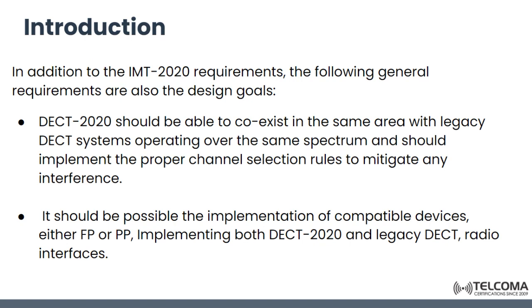With the help of DECT 2020, we can simply build our own private wireless network in which every node can be an access point with a direct backhaul connection to the internet. In DECT new radio 2020, this terminology is sync node. We call it a sync node. The lack of centralized setup and operation immediately enables self-organizing and self-healing mesh networking wireless topologies.